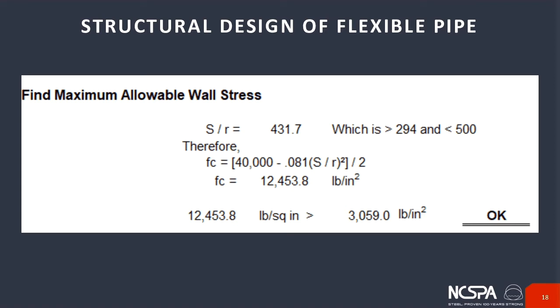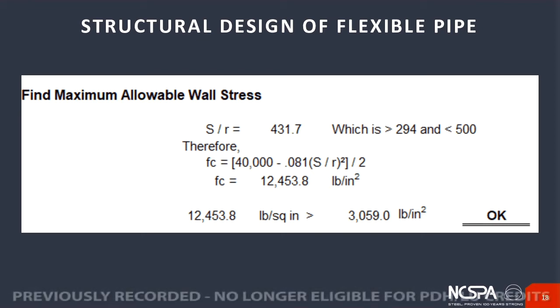For structures that were very beefy, in other words, they had a lot of compressive capacity and a very low slenderness ratio, those would fail just through axial compression.